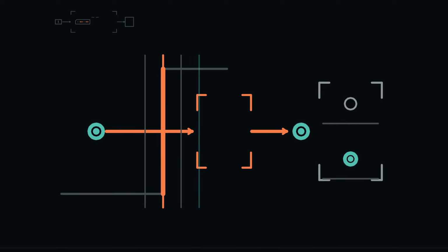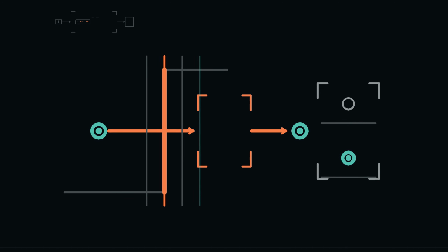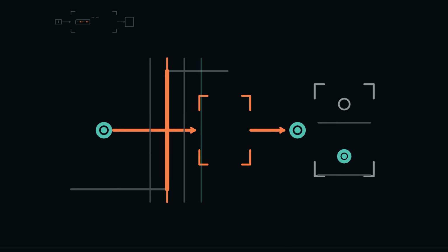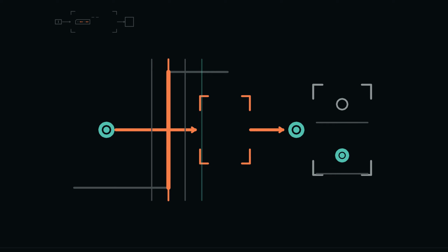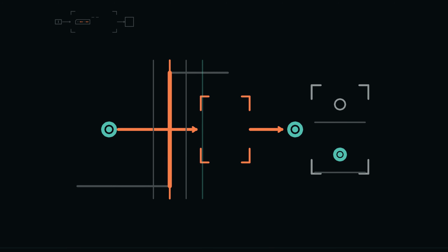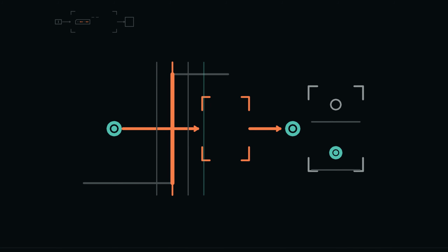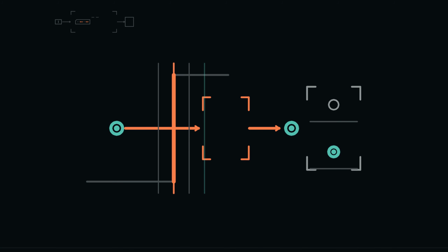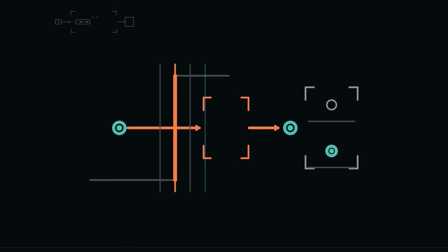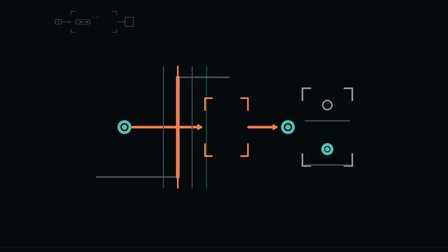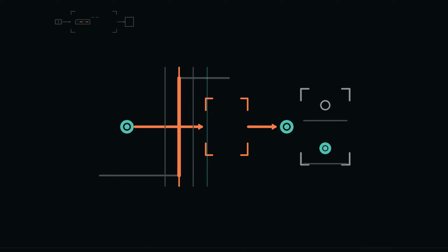Read the next 3 edge ledger before it runs. Initial Q is 0. D settles at 1 before edge 1, remains 1 through edge 2, then settles at 0 safely before edge 3. The predicted new Q values are 1, 1, 0. Notice that the second edge still performs a capture even though the visible value does not change. State transitions describe the rule applied at each event. A repeated value is not evidence that the clock was ignored.